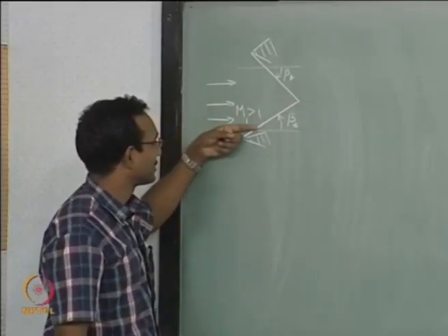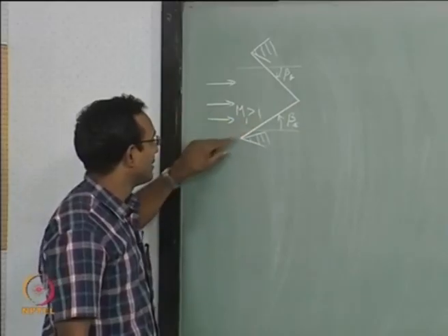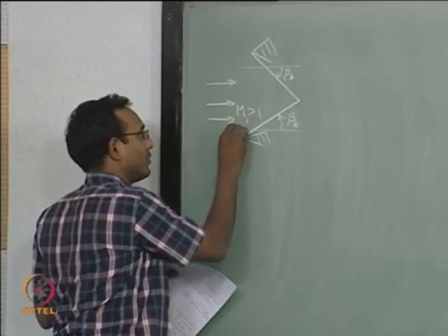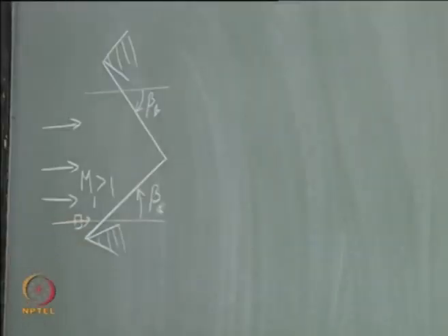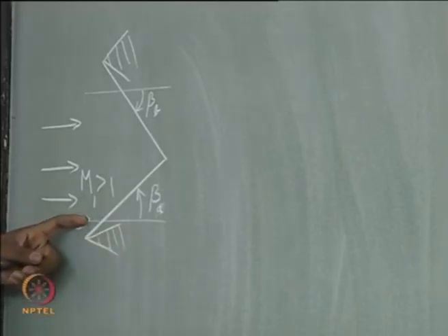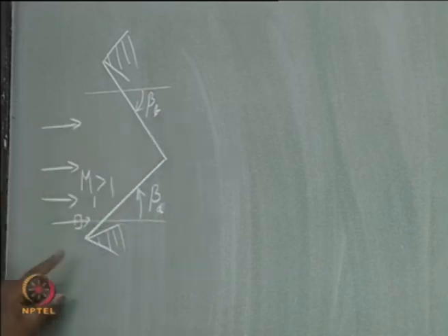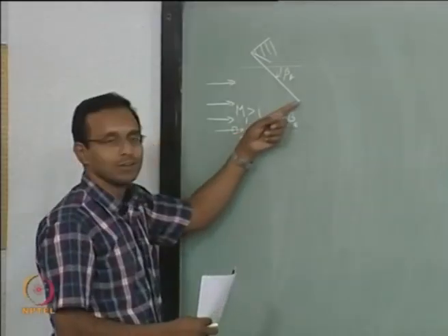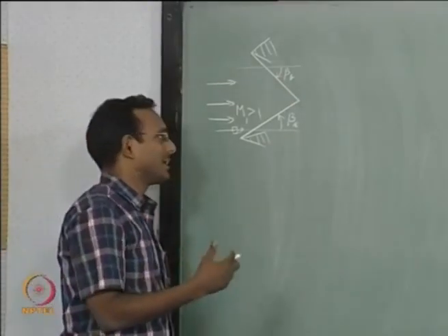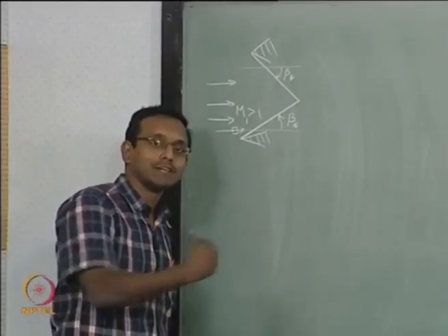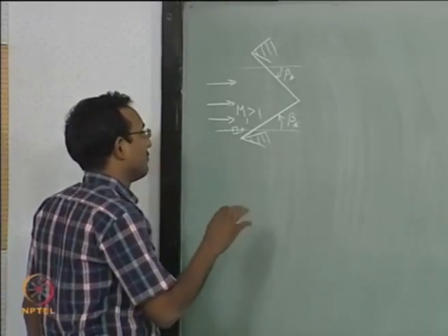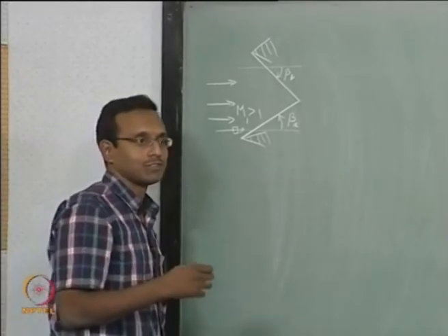If I am the fluid element standing here, facing the body, I am going to see that this particular shock starts from the right and goes towards the left. So it is called the left running shock, while that one is a right running shock. It came from the idea of method of characteristics, which we will introduce towards the middle of the course, but as of now we will just use that terminology, it is useful for us.